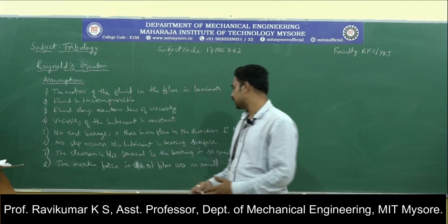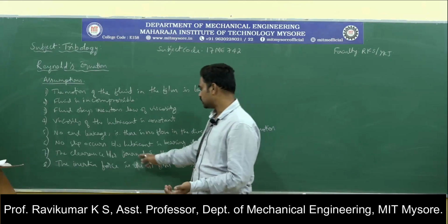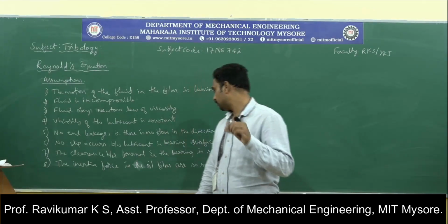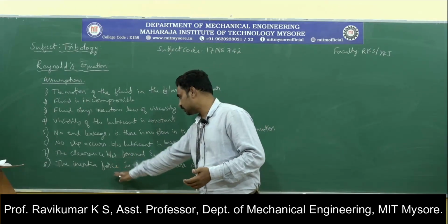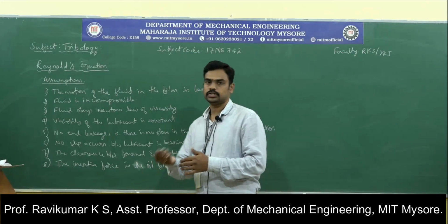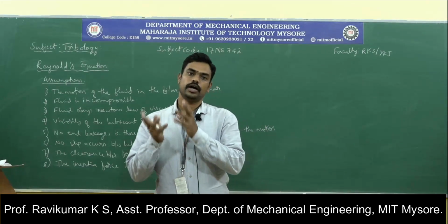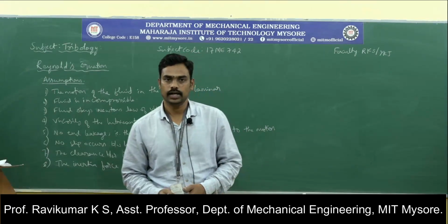Then there is no slip between the lubricant and the bearing surface. Then the next assumption is that the clearance between the journal and the bearing is small, and the inertia force is also assumed to be small. Thereby the effect of the clearance and the inertia force can be neglected.